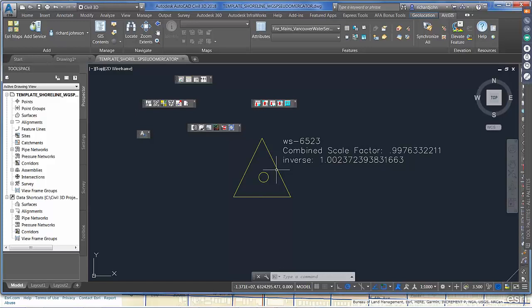If we were just doing GIS maintenance and we were adding data from a CAD file that had already been designed, we know that because we understand the data process, we already would have converted this design feature to a GIS feature by applying the scale factor for whatever survey control was used for this particular area. So anywhere in that process, we have to understand what it is that we're adding back to that GIS database and how we're adding it.